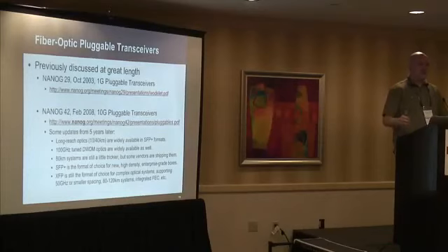Some vendors are not quite shipping them. There's definitely some minor nagging questions on heat and power draw and things like that. But give it a little bit more time, you'll see 80s be very common. SFP Plus is definitely the format of choice for anything enterprise, anything high density, anything top of rack type stuff. But XFP is still the winner if you want to do anything fancy. So if you want to do very narrow DWDM channels, if you want to do very long reach systems, integrate FEC, any things, and we'll talk about a lot of this stuff later, but it's still where you have to go if you want the good stuff.